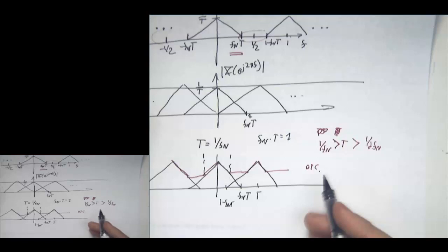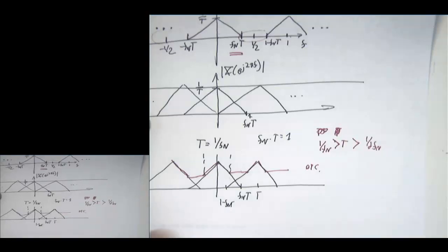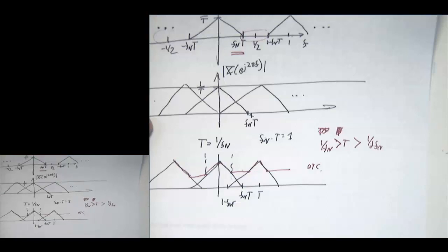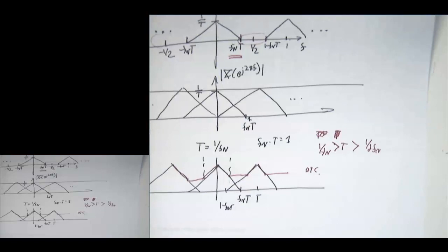Nyquist doesn't give us the whole thing, but it just happens that we could still possibly get something here. And this fact is used in a lot of the constructions of practical analog to digital converters, because you can oversample and you can play other kinds of tricks where even though there's aliasing, you can get around it. So that's the aliasing concept here. And that's what I wanted to illustrate now.